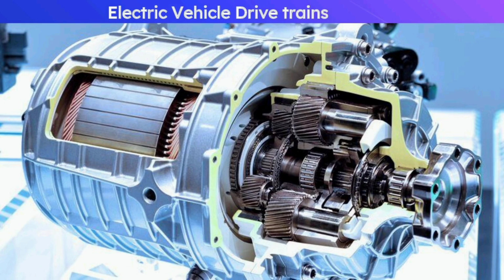State of the art electric vehicles use different kinds of automatic transmission such as two-stage gear drives, integrated stepped planetary gear drives, or continuously variable transmissions, also known as shiftless transmissions, to operate at optimum efficiency. Often, electric motors, power electronics, and drivetrain share a single housing, reducing the overall number of components in the powertrain and lowering the overall weight of the system.